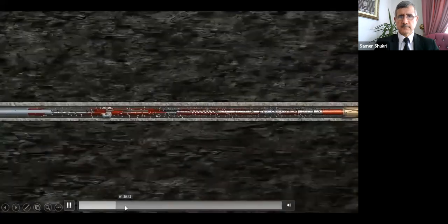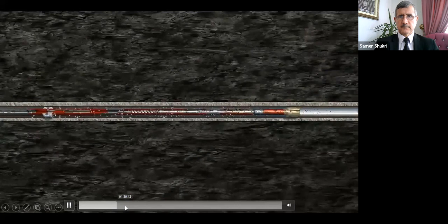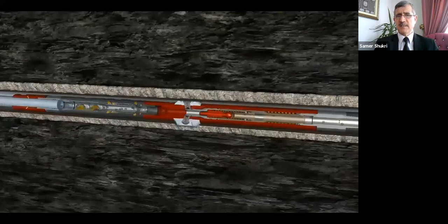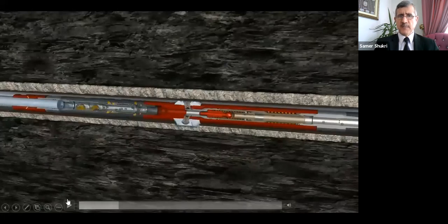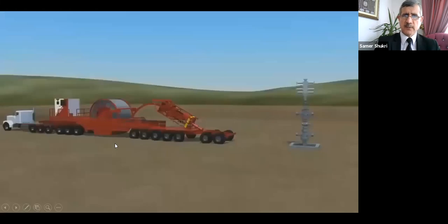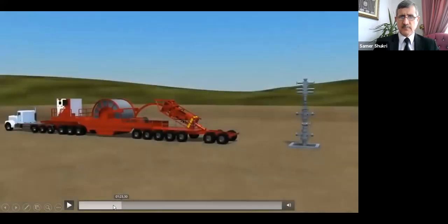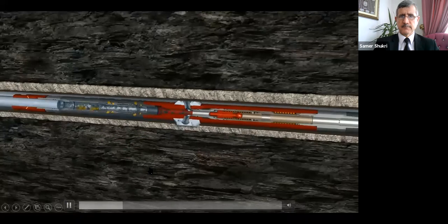Once clear, the BHA can be pulled up hole to the initial perforating location. So after milling the cement, which is a result of the rig, and removing it, we can pull the milling tool with the coil tubing up, and then we do the perforation. Flow out the carbide jetting nozzles.